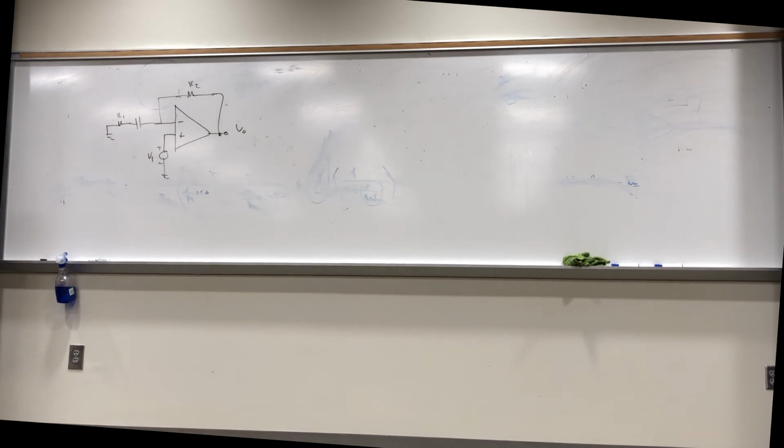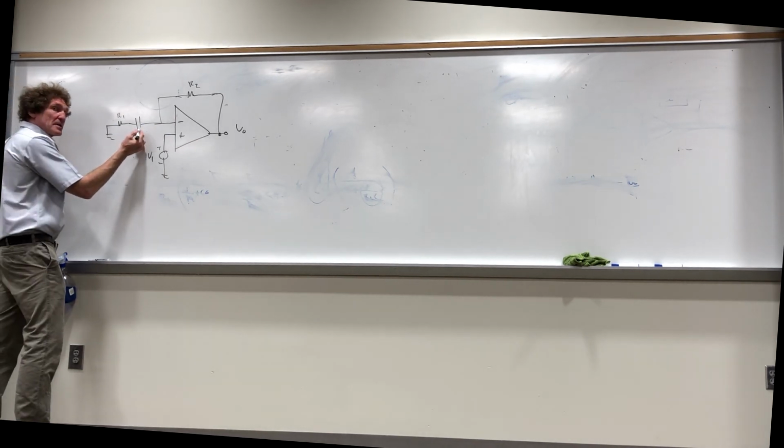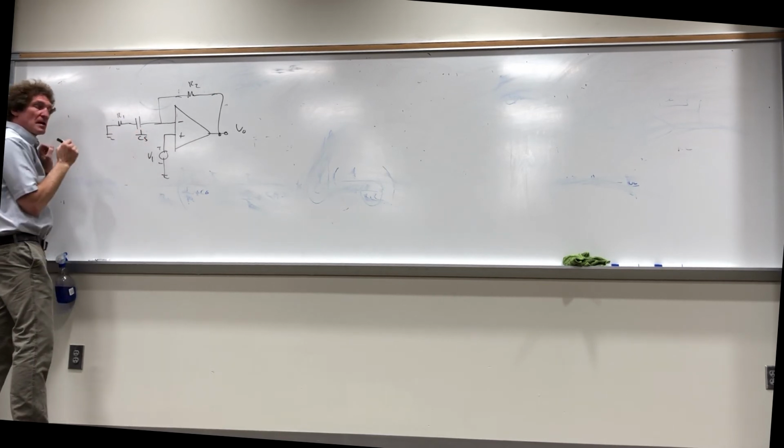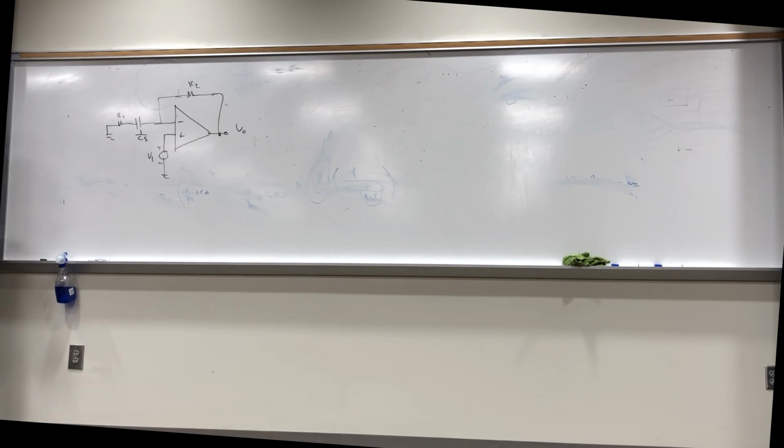All right, this is one you can probably see the answer for. Most of you understand this now. If this is the input voltage, right? Let's do this in the S domain, all right? Because that's the only way that makes sense. All right, we're going to do it in the Laplace domain. What's the impedance of this capacitor? 1 over CS, right?